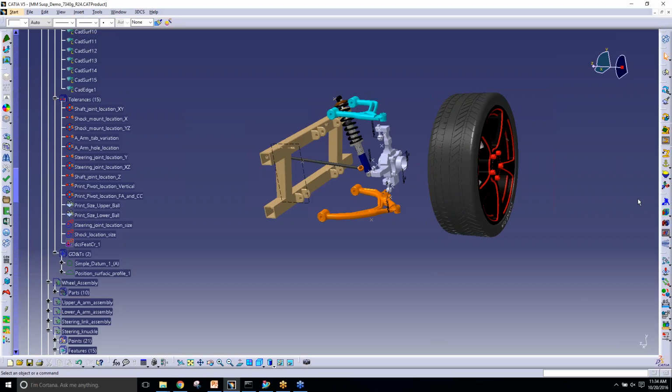So what would be a good application of that? Well, you have a fixture that's commonly used from one station to another. You've got an underbody that's going. So you would want to duplicate these same tolerances from one fixture to another that are identical. I know we're not planning on talking about that today, but when it's a total duplication, we can also use the mirror command, which will mirror all the moves, all the tolerance measurements as well. The copy data is commonly used when you have similar parts, not totally separate parts. Similar parts that are used, like a fixture.